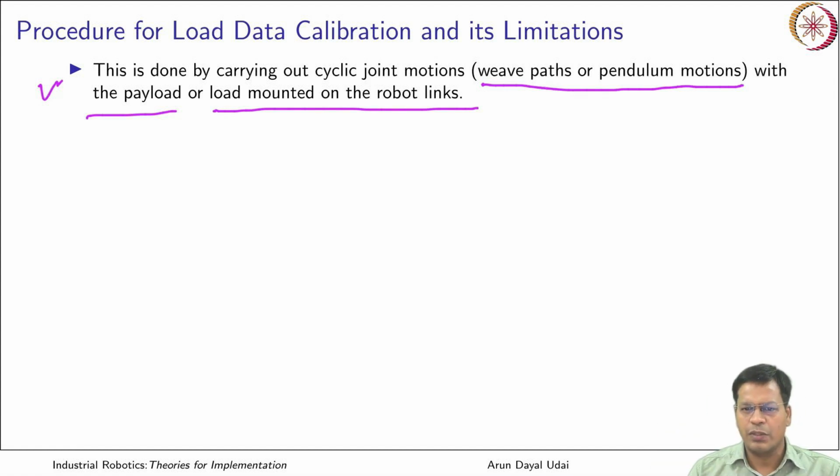Along with all those loads, the robot controller, or you yourself, can move the robot in a cyclic manner and observe the torque, note it down, and then you can calculate how much those supplementary loads are. A robot can do it with automated programs which are supplied along with the robot, or which come as an add-in plug-in to the robot controller software.